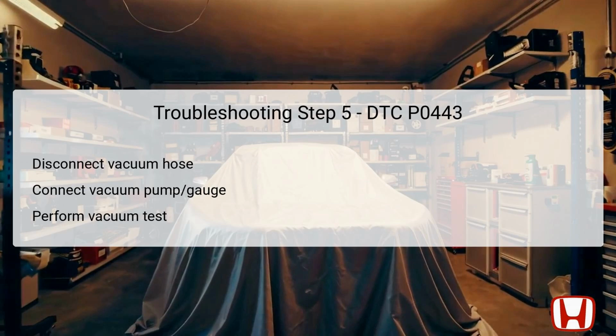Understanding the vacuum levels will help in determining the integrity of the purge valve, as proper functioning requires a certain threshold to facilitate the flow of vapors into the intake manifold. In this step, the technician will start the engine and allow it to idle, which is crucial for assessing whether a vacuum is present at the disconnected hose.